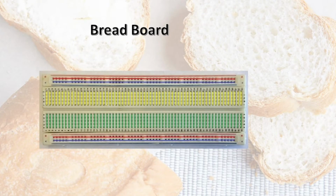Now let's see what this breadboard is all about. So this is the backside view of the breadboard. There are some metal strips connected at the backside, at the bottom side, which are placed in different order. Some metal strips are in a horizontal way and some are placed in a vertical way. So it's a simple plastic board and it is used for prototyping.